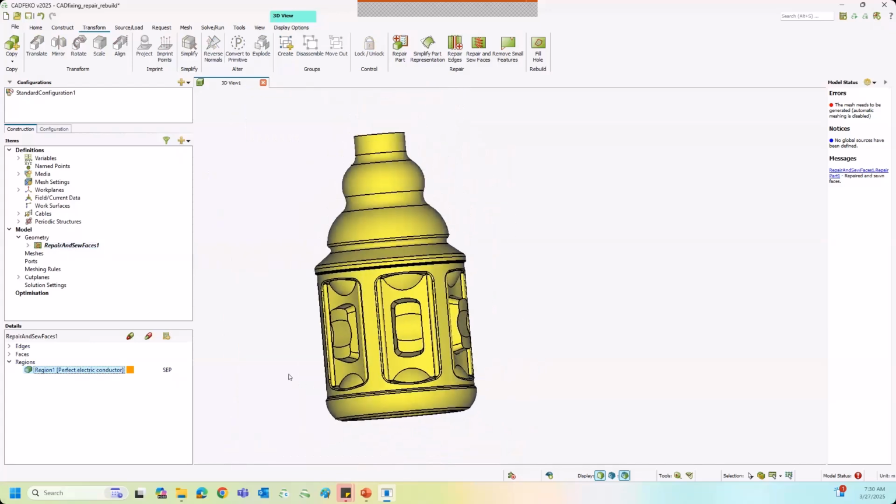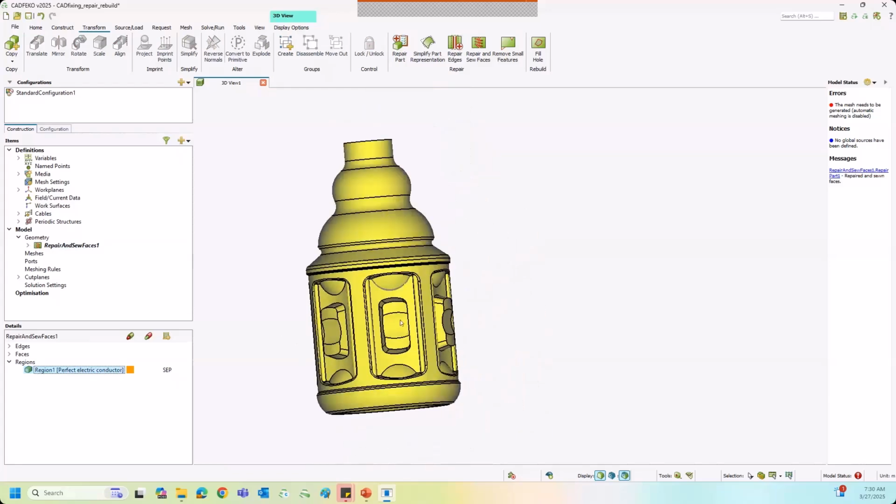Okay, so in some cases, let's say you're solving a model with a solver like MLFMM, and if you have a closed PEC structure, then you can use CFIE on it rather than the default EFIE, and a CFIE will help with faster convergence. So in those cases, to ensure that it is a closed PEC volume, we need to make sure there are no gaps in the model. So that is the reason we try to close the gaps.